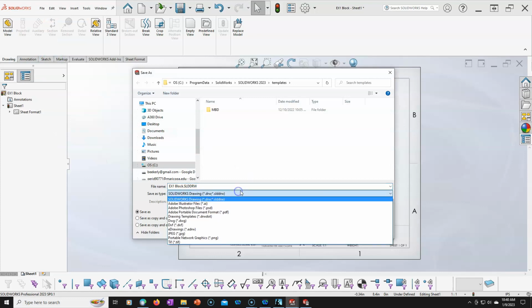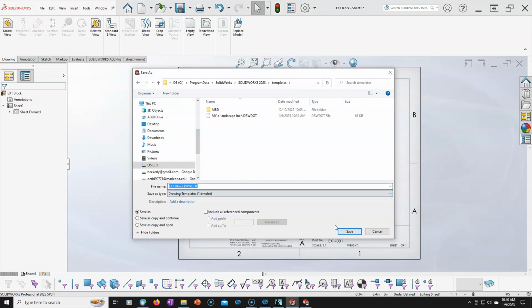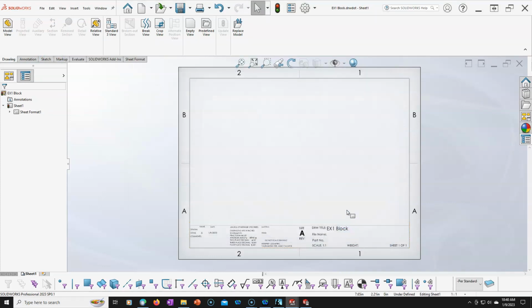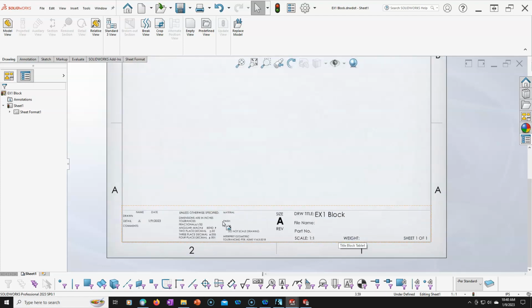So decide what you want in your title block, and we'll build it from there. And we'll take a look at some of the symbols, and actually I'm not going to have too much room unless I start shrinking some things up to maybe look at putting in the third angle projection symbol and maybe a default surface finish symbol.